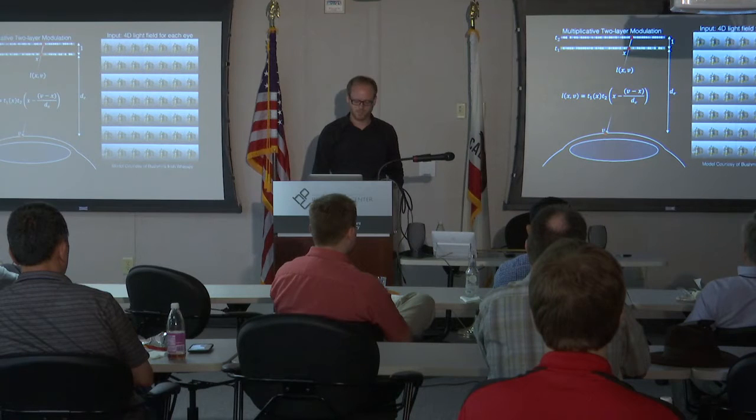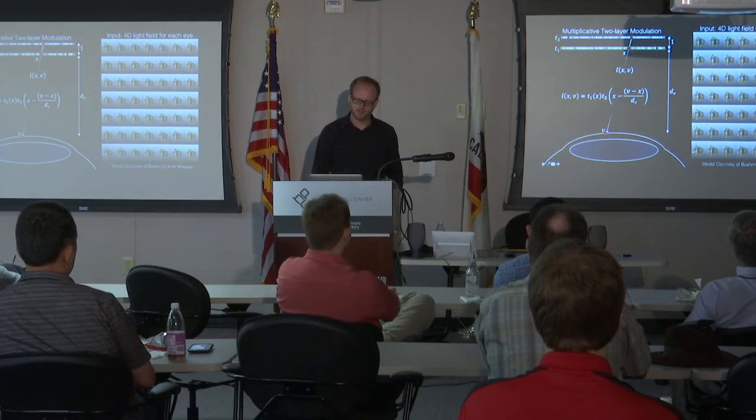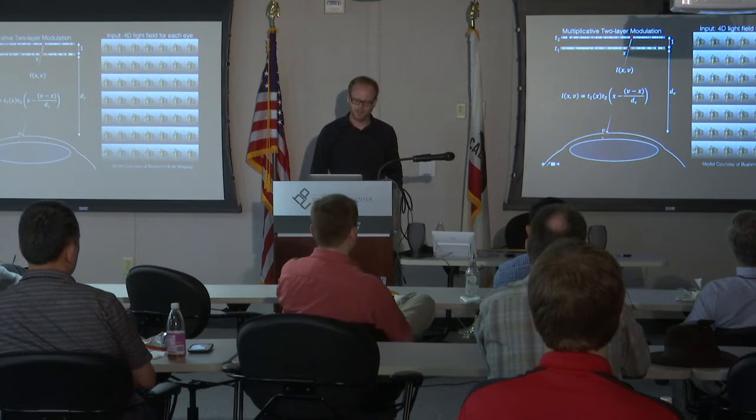We remove the backlight from this front LCD. It's different from having emitters. It's not the same as having a transparent OLED or using a beam splitter where all the lights add together. In this case, it's really this multiplicative effect that creates a nonlinear effect that allows us to potentially get the 4D light field back. So we represent the light as a multiplication along the ray,